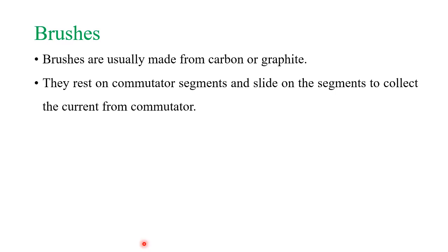And brushes. These brushes are usually made up of carbon or graphite. They rest on the commutator and slide on the commutator segments to collect that converted unidirectional current to the external circuitry.